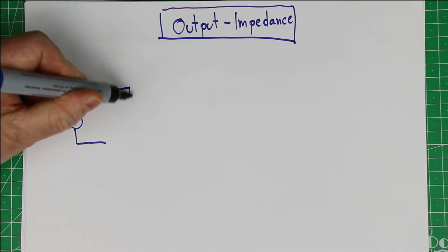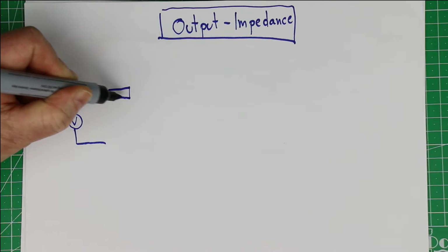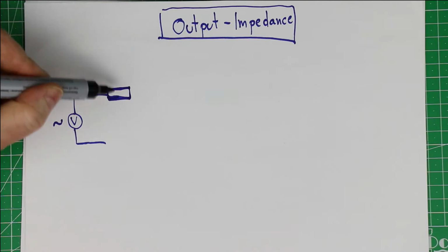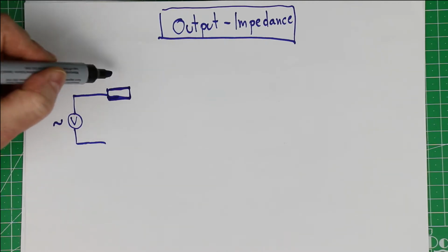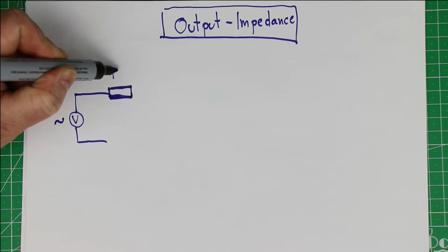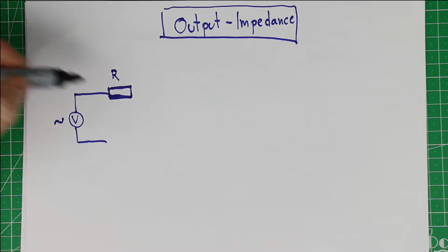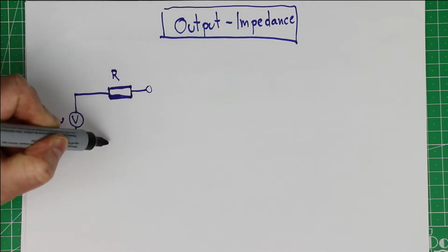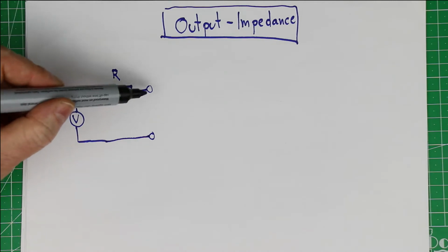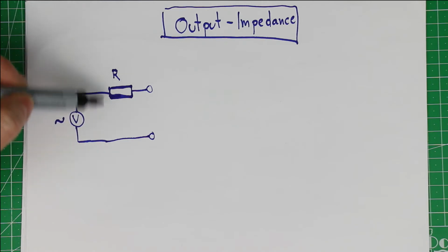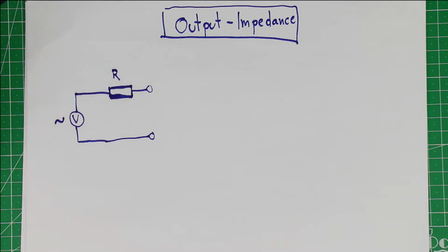And you can suppose the output impedance will only deal with the resistive part and not do any complex calculation. So let's suppose we have an unknown output impedance R, which is in series with your output driver stage. And here you have the terminals that could be an RCA jack or whatever. And now, when you don't get inside and don't have the circuit diagram available, how do you measure what output impedance you have?